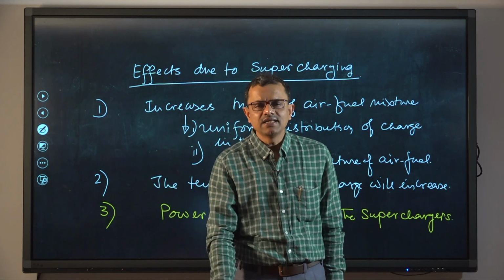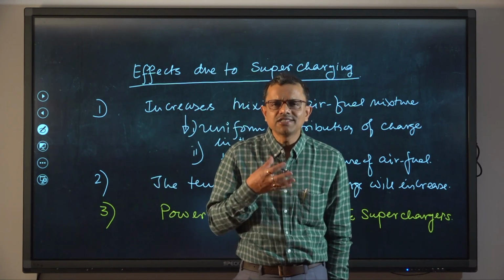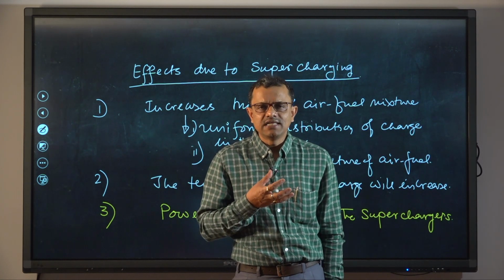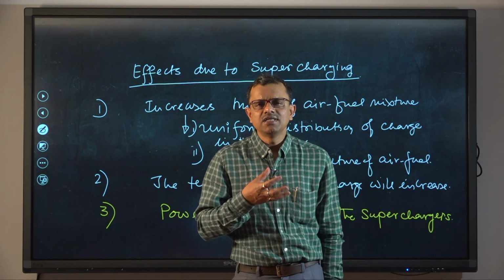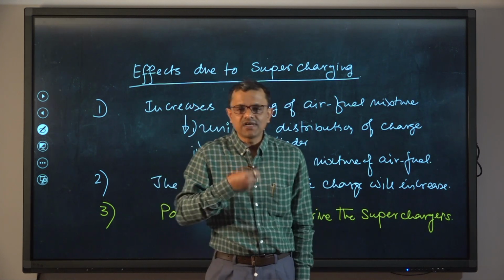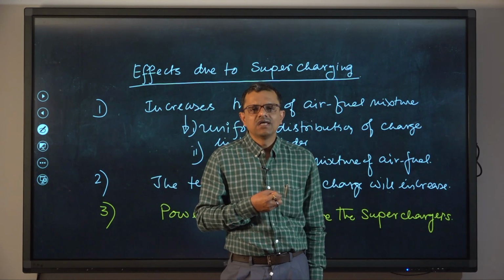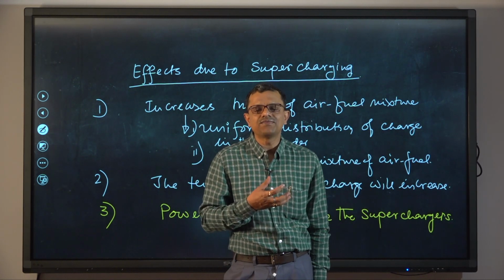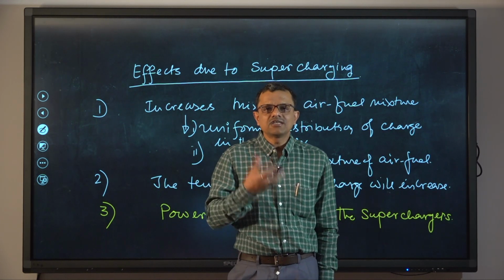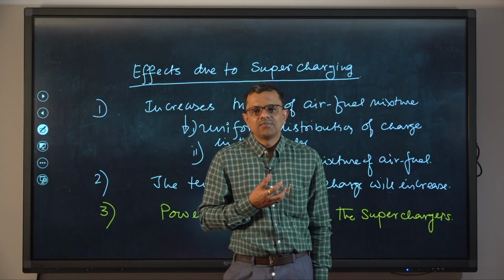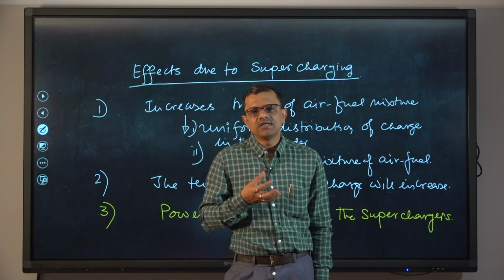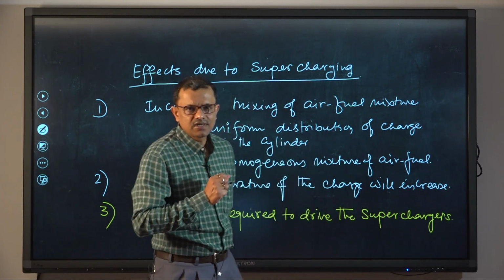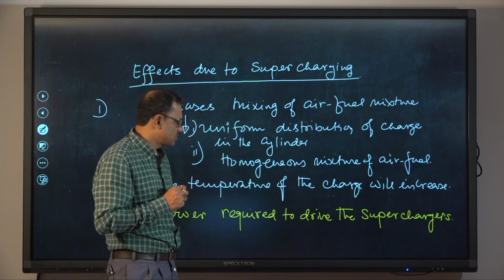Let me repeat once again. It will promote vaporization of fuel droplets in the intake manifold, but rise in temperature will increase the temperature of the charge even further during compression stroke, and that eventual rise in temperature may become vulnerable for the onset of detonation for the SI engines, but this rise in temperature will reduce the possibility of having detonation for the CI engines that you have studied in your undergraduate internal combustion engine course.